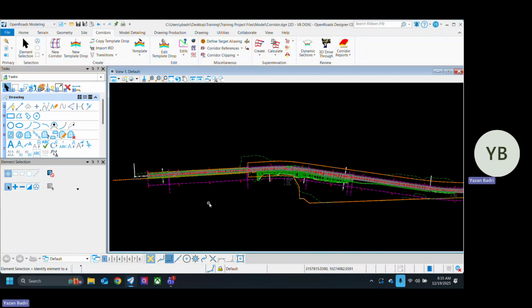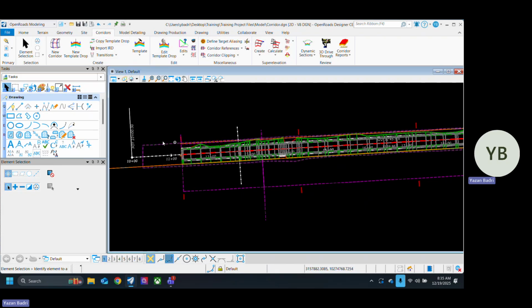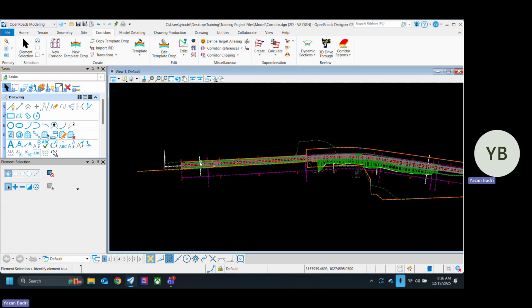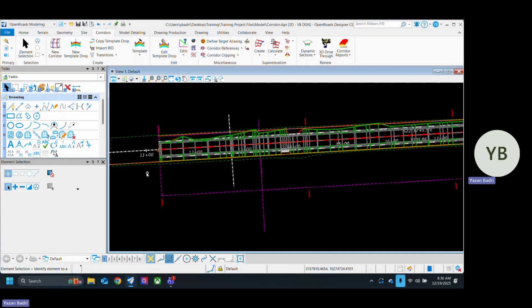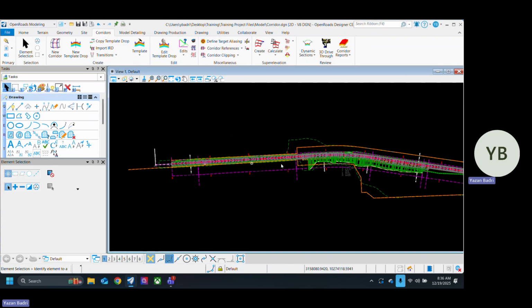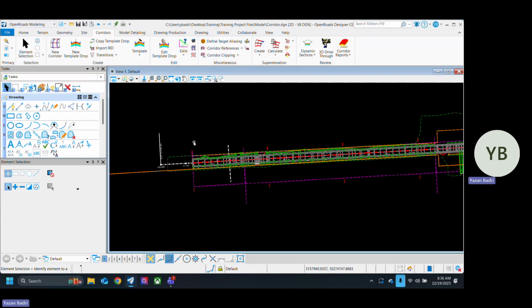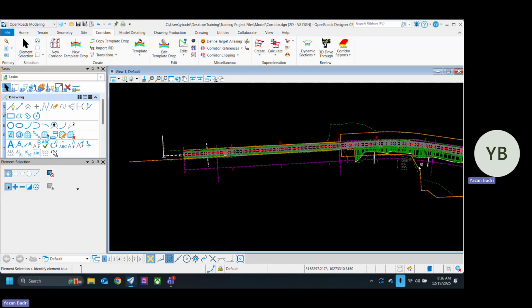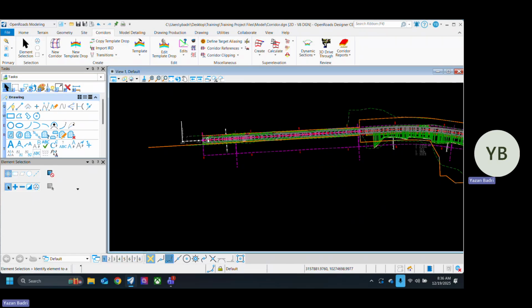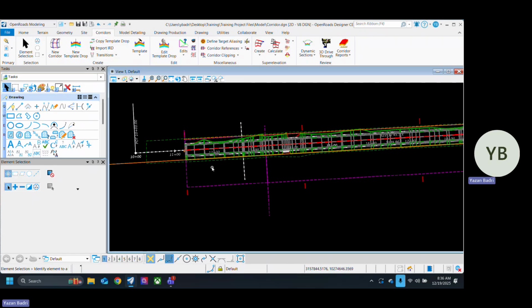All right, so yesterday we started with terrain models, how to import the existing terrain. Imported the TIN. We looked at how we can modify it and all that. We then created the horizontal alignment using the horizontal alignment tools or horizontal geometry tools. We then created a profile for that alignment and activated it. And then that was everything we needed to run a corridor.